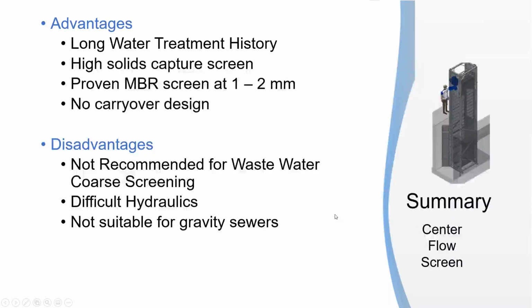Then lastly, the center flow screen, very long water treatment history, growing wastewater treatment industry, but primarily for the MBR style screens, does have a good no-carryover design that results in a high capture rate. But because of its vertical orientation, not as recommended for wastewater core screening. It does have some difficult hydraulics. You want to make sure you get those right so you don't have issues upstream.